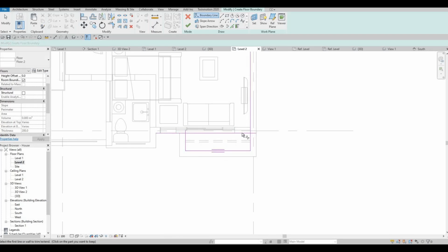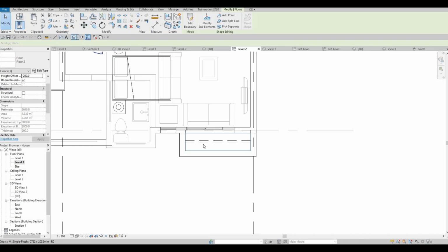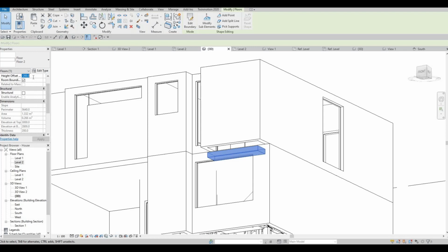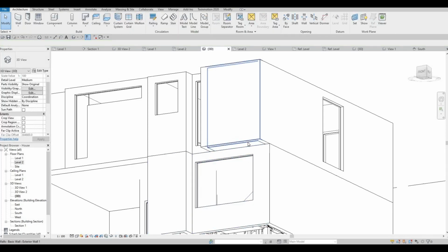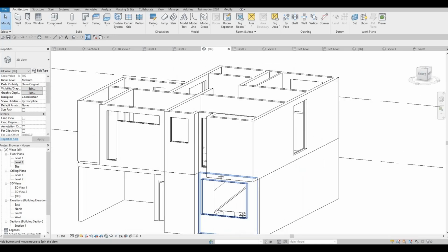From the inside, use TR, and before you do that, height offset, it should be 200 so that it's flush. Don't attach, and right here it's not -2, it's supposed to be 200, not negative. So now it's flush like that. So that's good.